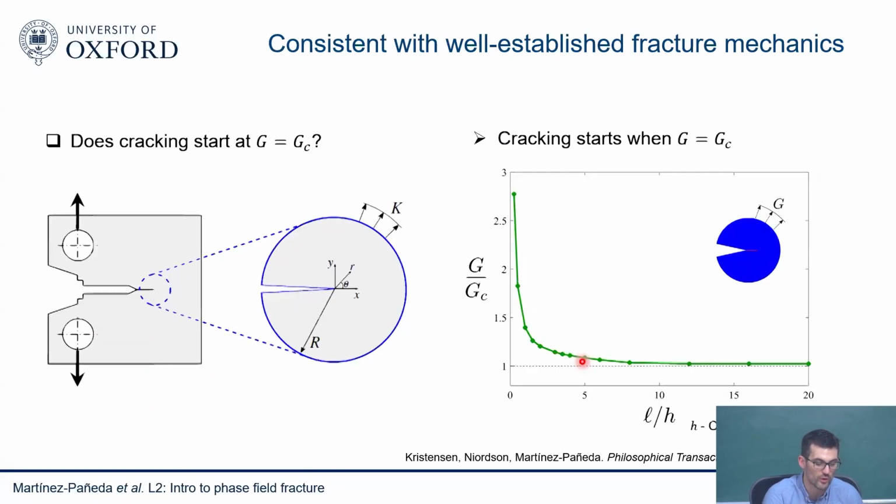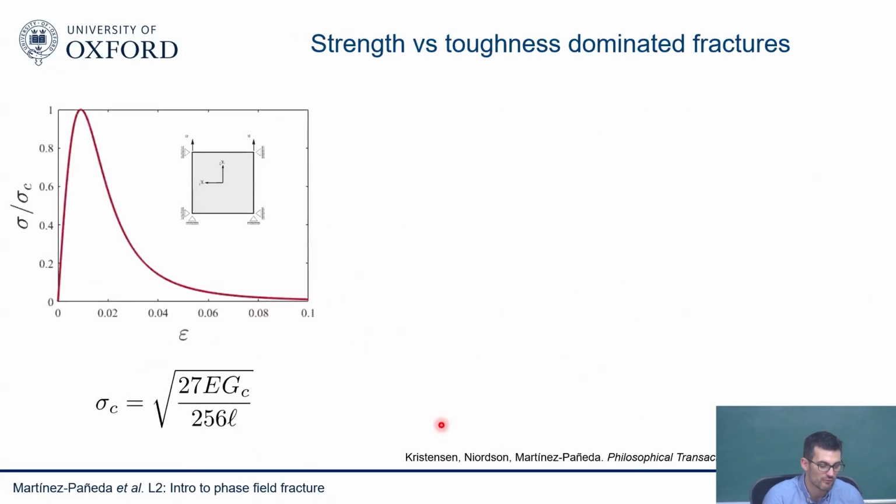And then of course a good question is, the original phase field model gives you this formula. Is this the right formula? Is this the formula that relates fracture process zone to strength, or is there a better formula? Should I follow something like this, or should it be slightly different? I mean, that is up for grabs. It's a bit difficult to correlate. We know roughly it's the right approach, but there are other phase field models like the phase field cohesive model. The differences are small, but I'll discuss them later. But yeah, you could say every time I need to do it, I'll just apply this formula.